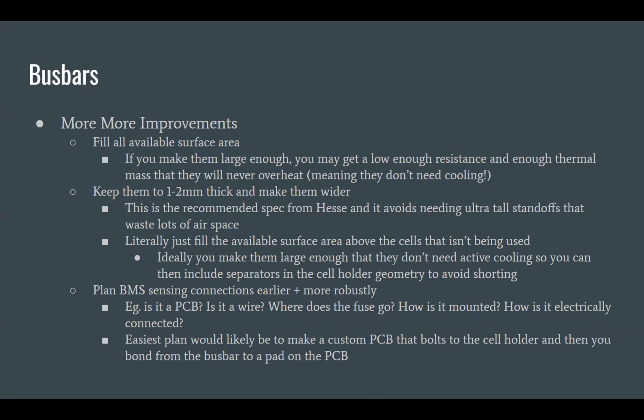They say that they can bond higher ones, but they strongly recommend it. It's way more efficient, way more standard to make a thin 1 to 2 millimeter bus bar that spreads out rather than having one thicky boy. And that then lends really well into the larger design guideline of try not to send your current down and then through a tiny strip and then back up. Instead, try to have it evenly go throughout the pack. That could potentially be more difficult. So that's the thing.